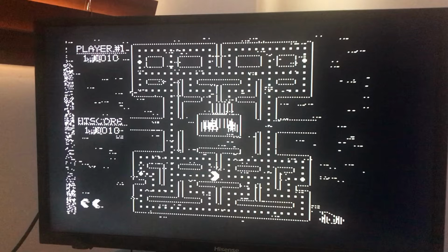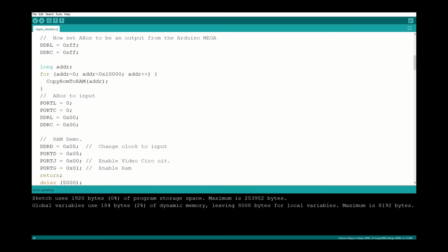The CPU does appear to have written to the memory. We can see this character 1 under both high score and under player. It's just written in the wrong spot. So I think the conclusion we can draw is the memory either starts corrupt or gets corrupted as the program runs. So this derives the first test I want to do.